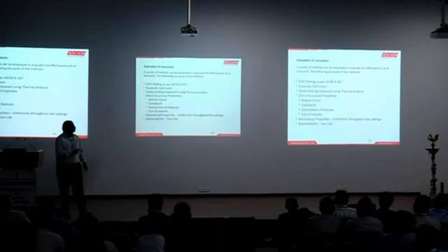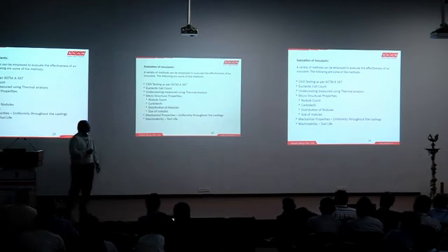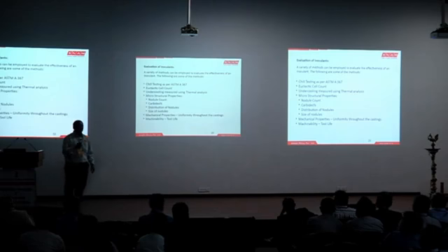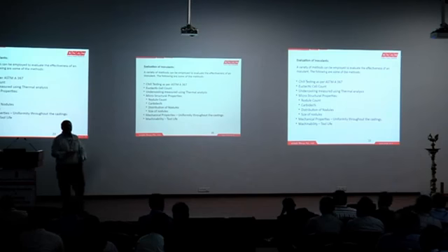So how do people evaluate inoculants, or how is inoculant efficiency being evaluated? There is the chill test. It's a very old known test, and I've heard people telling that just by looking at the width of the chill, they will be able to predict and exactly adjust the carbon level, carbon equivalent level, and they can even predict the carbide forming tendency in the casting. And eutectic cell count.